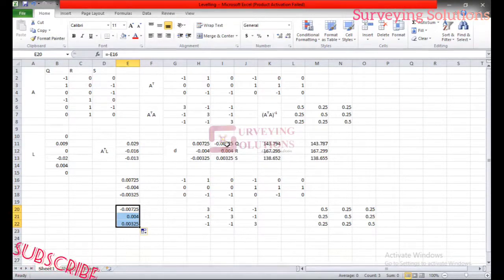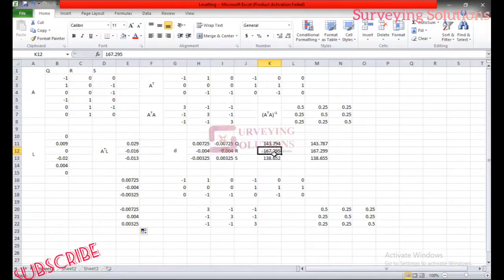So that's the same thing as this particular column. The final part is now the adjusted height of each of those points. We already have the observed height, which we calculated using the benchmark. Remember that that of Q was 143.794, that of R was 167.295, and that of S was 138.652.